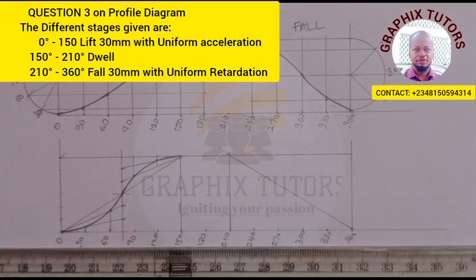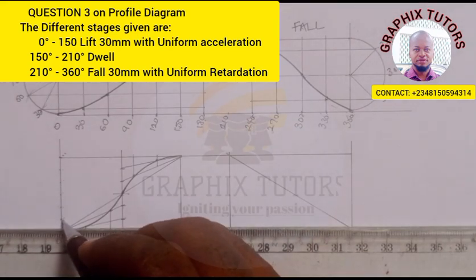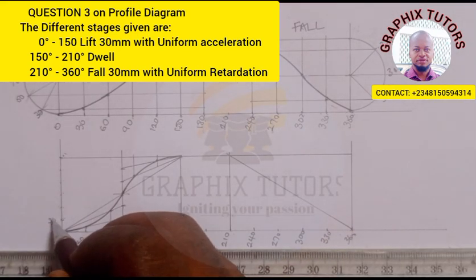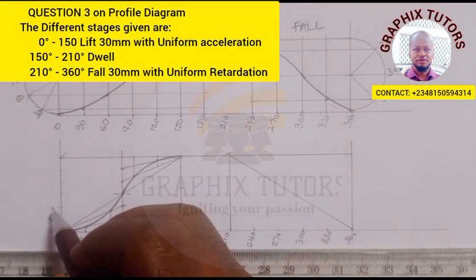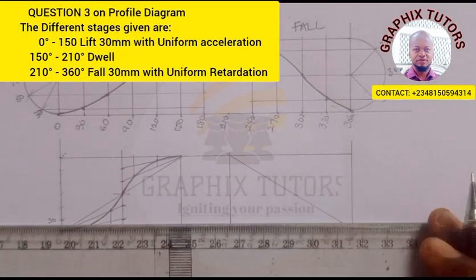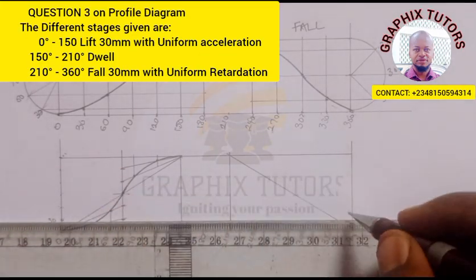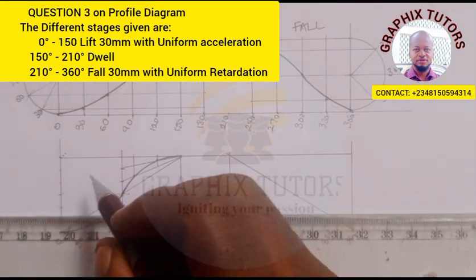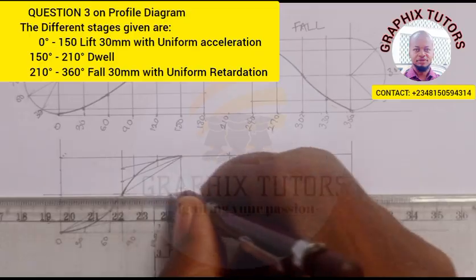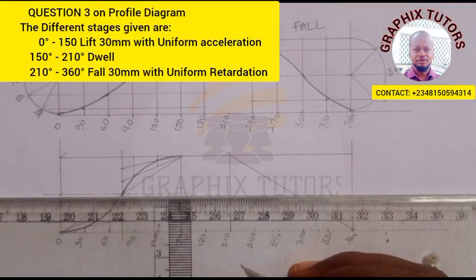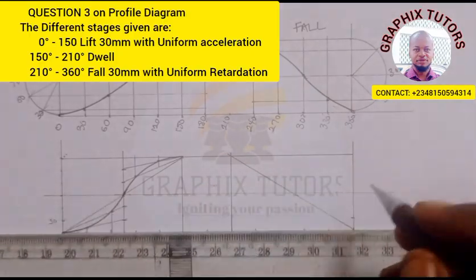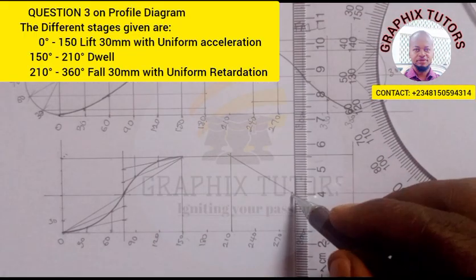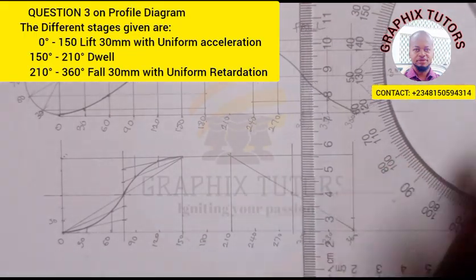The same thing happens. All these points you see, let's see, this is 0, this is 30, and so on. Let's see, this is what we have. Then this point, I'll transfer it from here to cut here. I just need the midpoint. This is the midpoint here. Right? So the midpoint is coming all through here like this. So from that midpoint, I'll draw this up this way.